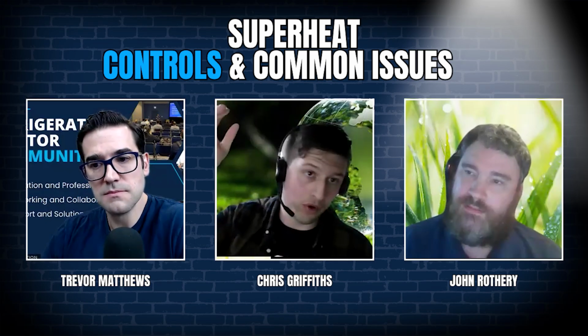What are your guys' thoughts? Exactly what I'd recommend there is, where possible, particularly on cold rooms or walk-in freezers, if you can access above the room at the top of the suction riser, put the transducer there, because ideally any oil which has made its way up there will then continue to flow back to the compressor. It's not like if we sat it at the bottom before it rises up that riser, where any oil can pull back down and potentially flood it.